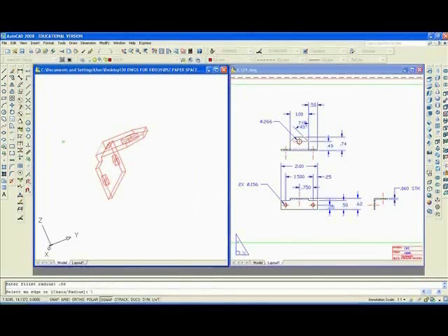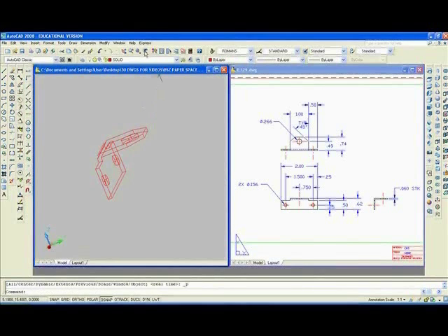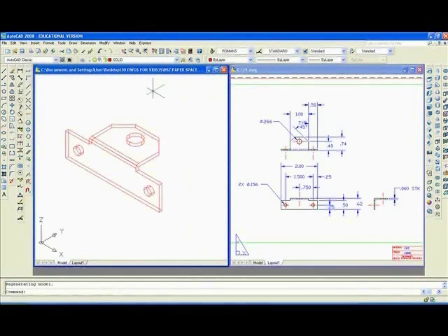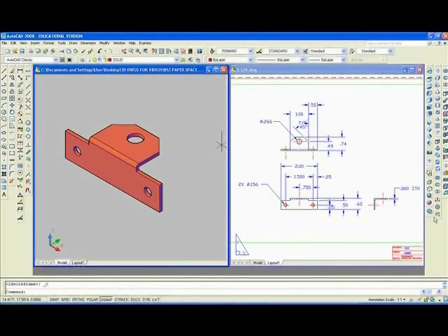0.06. Try it again. 0.06, enter, enter. All right, so I'll zoom previous now, and zoom previous again, and we'll try it one more time. That looks right now. The radius is on the outside of the bracket.